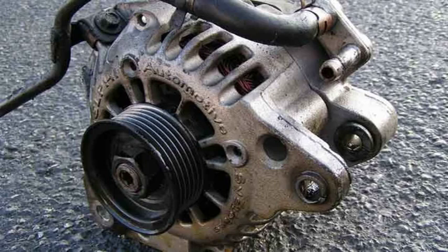Slow or difficult starting. If your car is slow to start or cranks but doesn't turn over, it could be a sign of a weak battery caused by a faulty alternator. Burning smell. In severe cases, a failing alternator can produce a burning smell due to overheating. If you experience any of these symptoms, it's important to have your car's alternator checked by a qualified mechanic. They can perform various tests to diagnose the problem and determine if the alternator needs to be repaired or replaced.